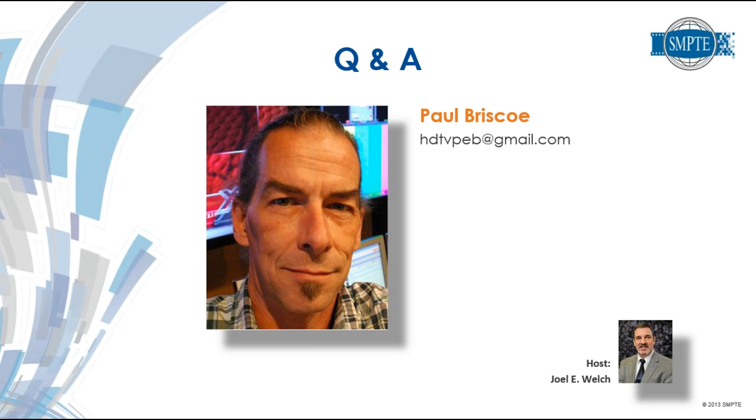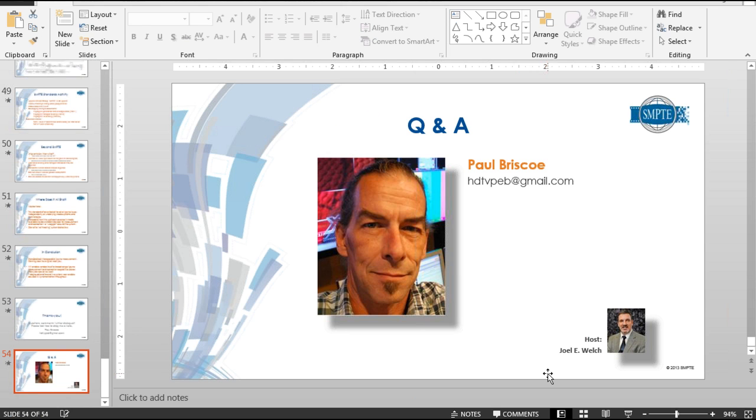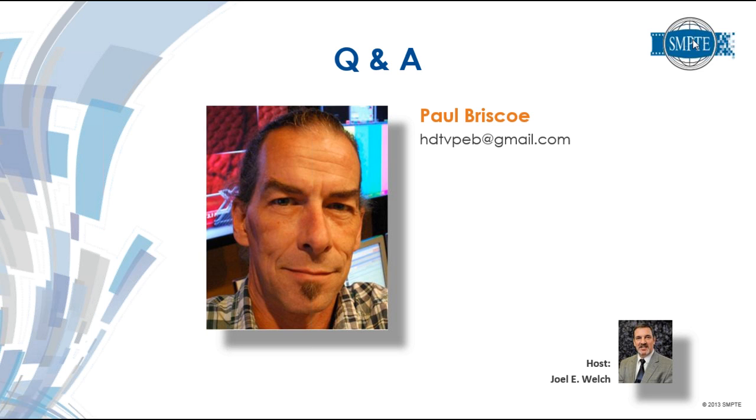In that particular case, and I didn't state this clearly enough, in the case of video fields, we actually have 2 video fingerprints in the payload per video frame. So they're transmitted on a video frame basis, but if you're coding fields, then there are 2 fingerprints in that frame. So at the far end, you can still take a P frame that would be temporally associated with one of the I fields upstream, and you can correlate them. Your correlation factor will drop by a factor of 2, because of course you have half as many pixels, but again we're looking at big, fuzzy-ish chunks of the picture here. So the correlation going to and from progressive seems to be just fine.